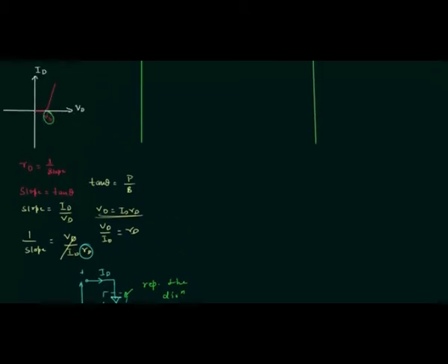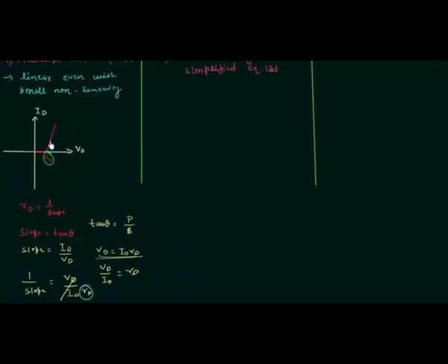So let's try to find the diode resistance. I will take one example in which at 0.8 volts the diode current is 10 milliampere, and we have to find the diode resistance RD. It is very simple. RD is equal to 0.8 minus 0.7. The barrier potential in case of silicon is 0.7 volts, and in case of germanium it is 0.3 volts. So we have 0.8 minus 0.7 divided by the current, which is 10 milliampere at 0.8 volts, and it is 0 milliamperes at 0.7 volts.